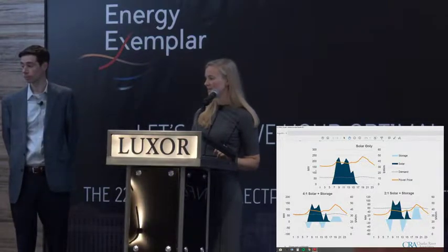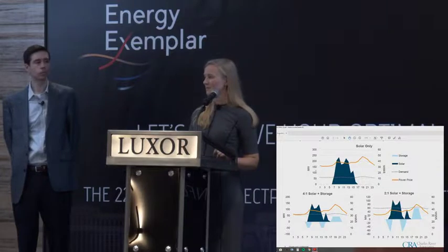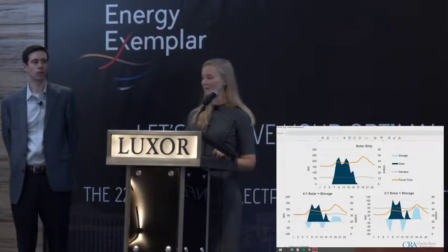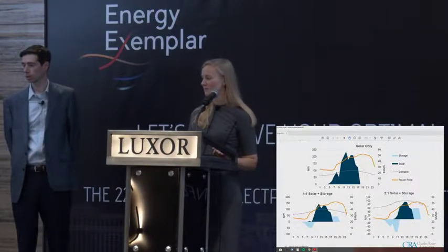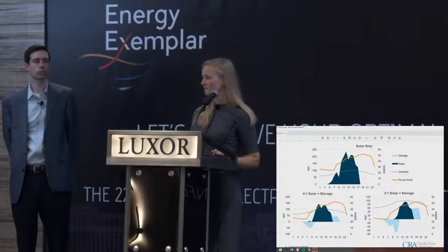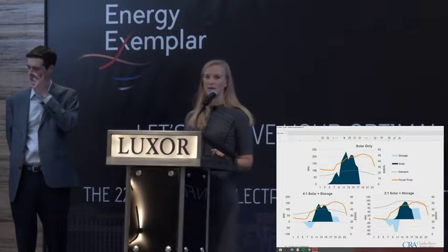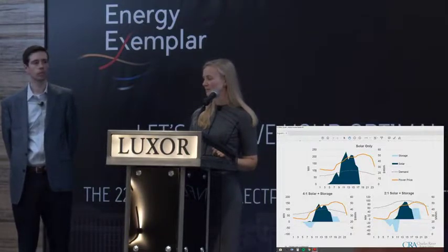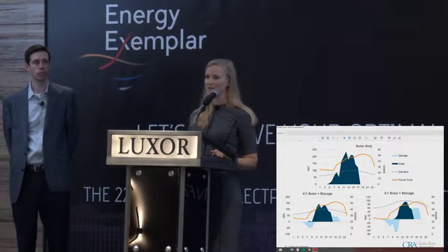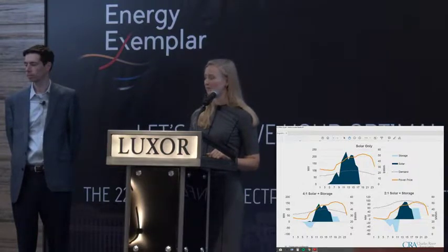So this slide is the summer day. Fairly similar thing, although we're seeing the charging happening only in the morning, and it looks like it's outputting a little bit earlier in the afternoon as it hits that afternoon price spike. Yeah, and they're a little bit more exposed on the load, it looks like, in the summer afternoon. So even with the 2-to-1, just based on their load profile, there's still a little bit of price risk exposure there. So they potentially would need even more storage if they wanted to fully cover their load on a hot summer afternoon.